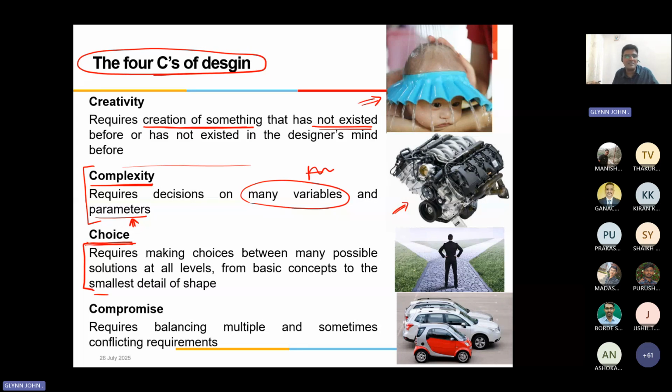So for smaller sizes, for a particular shape, you can choose one particular process. For example, if it is a cylindrical component, you will choose turning as a process, right? If it is a slot that has to be cut, then you can use milling as a process. If it is a thick component, if it is a thin component, a simple laser cutting will actually help you, right? So depending on the nature of the component design, the size, and the material, you have to make choices. And once you make that decision, it's very difficult to change it also, right?